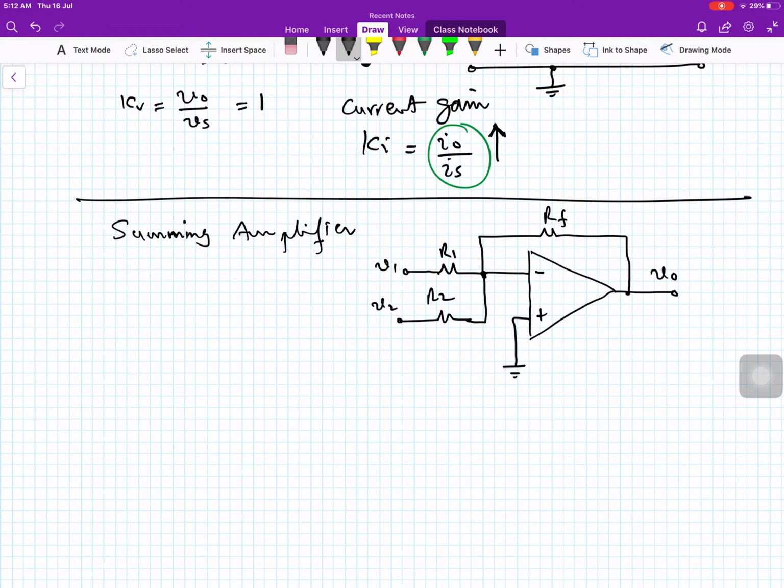This is very important. You will learn the reason for connecting the feedback to the inverting input for negative feedback. Now, what we have assumed is that the current I entering the inverting input is 0. Likewise, the current entering the non-inverting input is also 0. And we are also saying that Vp minus Vn in the ideal model is 0. Vp is equal to Vn.